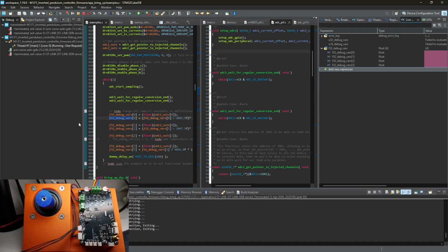No. Like, it's not a huge motor per se. There are motors that are gigawatts in wind turbines, but it's quite a heavy motor for an individual to have and to work with. This is around the dangerous territory of not using 48 volts. I'd say this motor I showed is right around the limit after which you need more than 48 volts, and 48 volts is the safe standard when you don't need to be certified to work with the voltages, to develop the electronics for such voltages. 48 volts is still safe to work with.